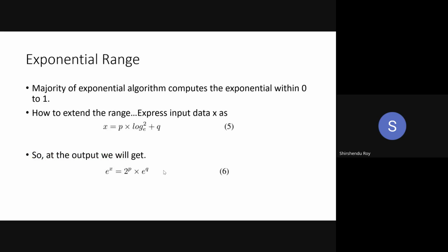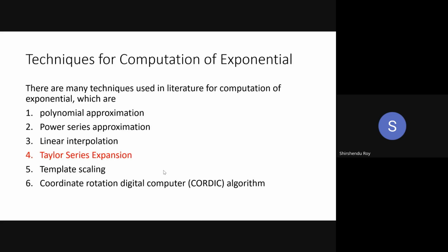Now what is very important in all these techniques is the input range of the exponential block, which is 0 to 1. That means you cannot compute the exponential of any arbitrary value greater than 1 or less than 0. You cannot compute the exponential for 5, 6, like that in hardware, because the input to the exponential block should be 0 to 1.